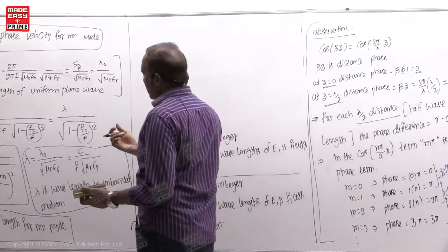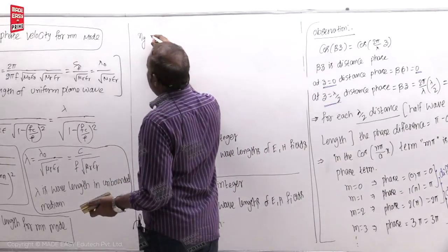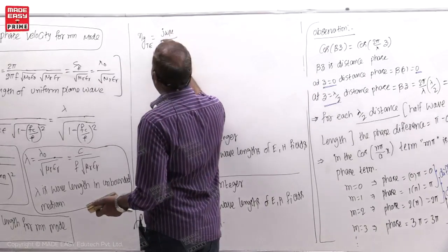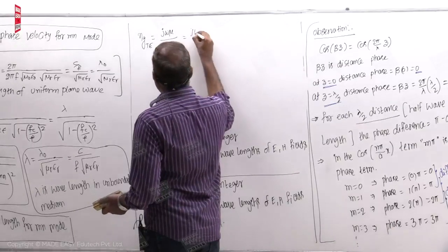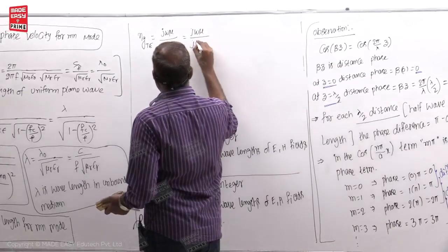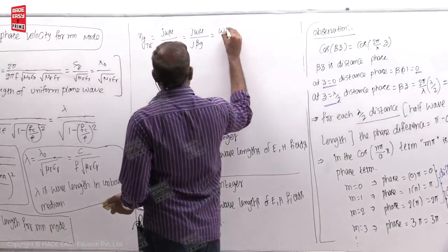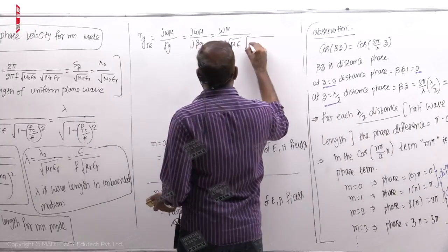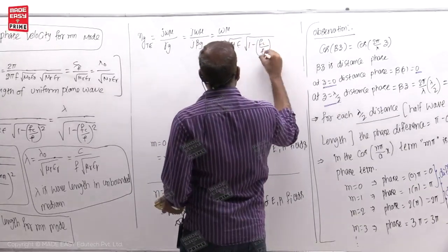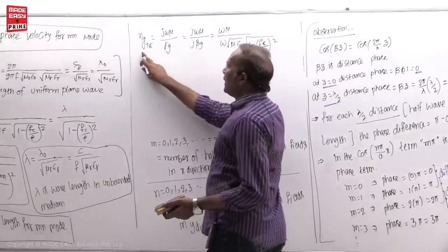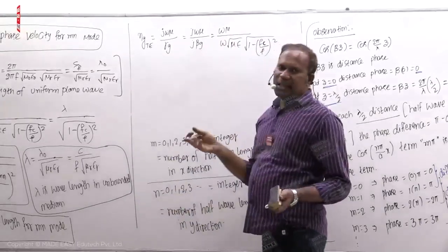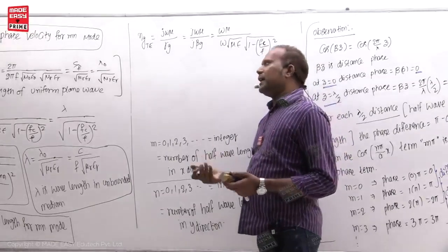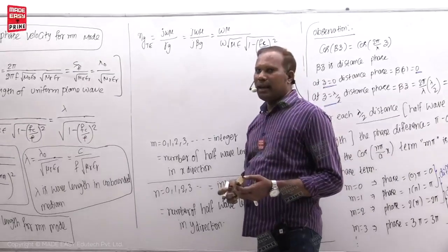Impedance equation. In the derivation of the impedance equation for TE mode, I got j omega mu divided by gamma g, and j omega mu divided by gamma g is j beta g; the j cancels, omega mu, and beta g is omega root mu epsilon times root of 1 minus fc by f whole square. You simply need not do the derivation, because eta by this beta g in the denominator means eta by that factor will come in the denominator. So eta by root of 1 minus fc by f whole square will be the answer.